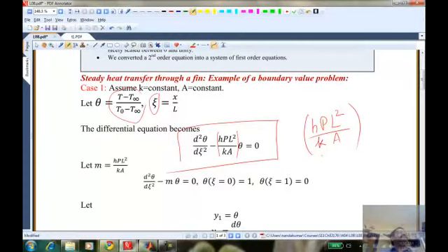And when that dimensionless number is 1, for example, this says that both the mechanisms are about the same order of magnitude. They are equally important. For example, if we call this m, if m is equal to 1, what is the physical meaning that we can attach to it? Well, the numerator has h. What does h stand for? Convective heat transfer. That is the rate of heat loss from the fin surface to the air. Okay. In the denominator, we have k. What does k represent? Conductive heat transfer from the base of the fin to the tip of the fin.